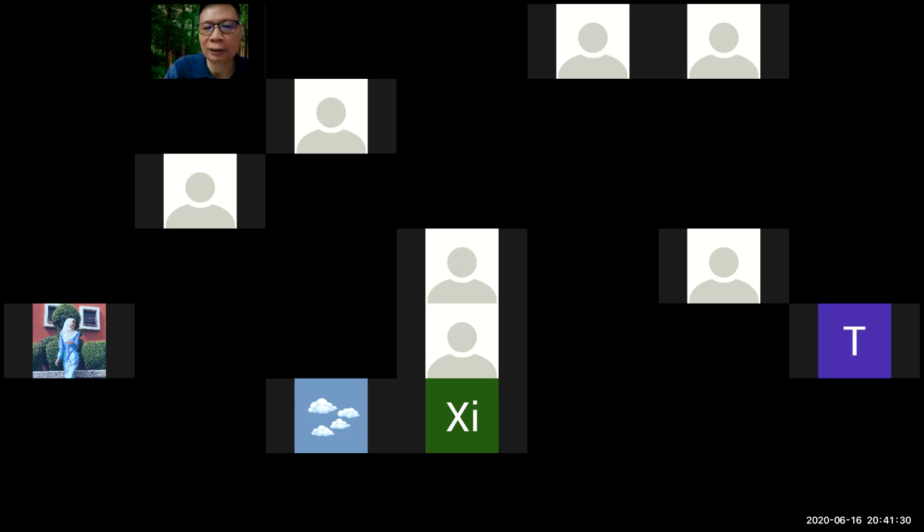Leakage of magnetic flux. How to overcome it? How to reduce the leakage of the flux? Winding the secondary and primary coils on top of each other. Yes, correct. Winding the primary and the secondary on top of each other. That's very good.